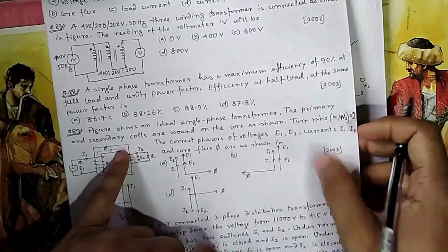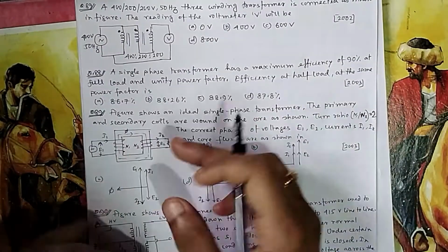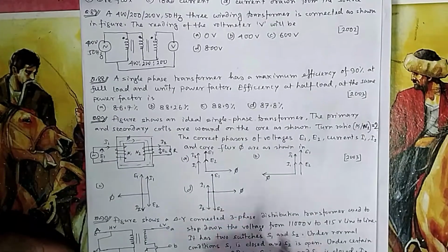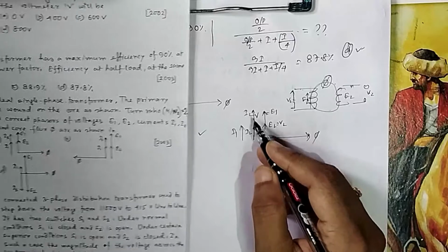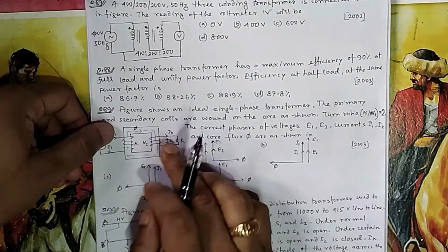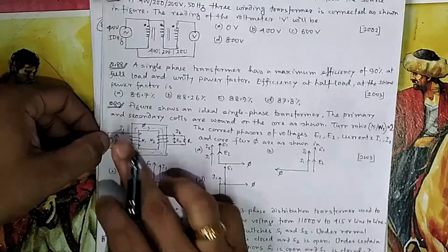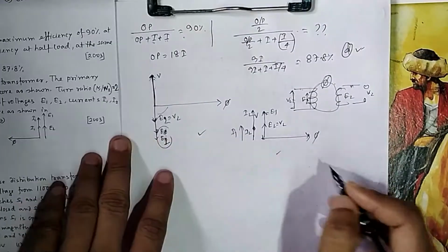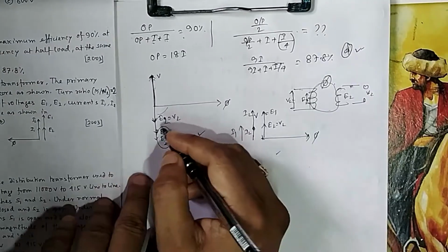In ideal transformers I am taking the magnetization current as zero, negligible magnetization current, so whatever I2 is, I1 comes in the same proportion. Otherwise, I2 would come here with proportion, plus Im would give you I1, which is not required. So both of these are correct, you can think of it either way.